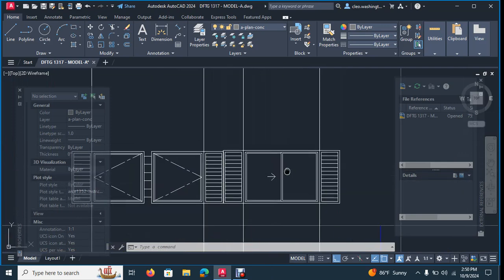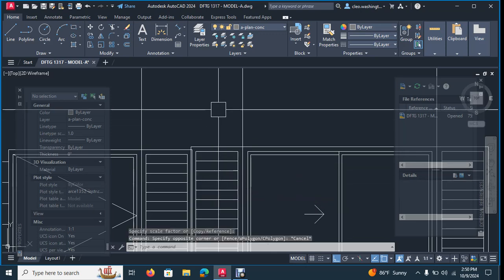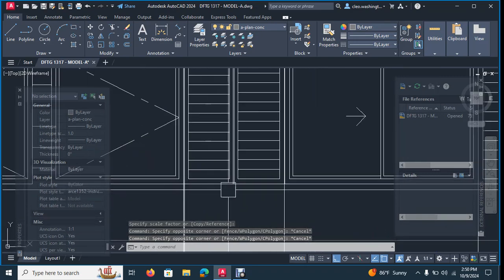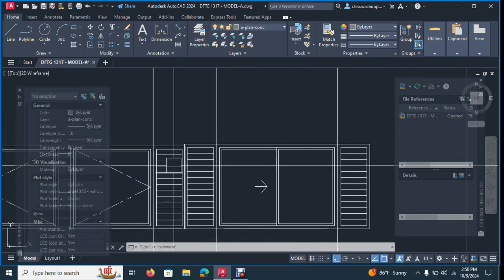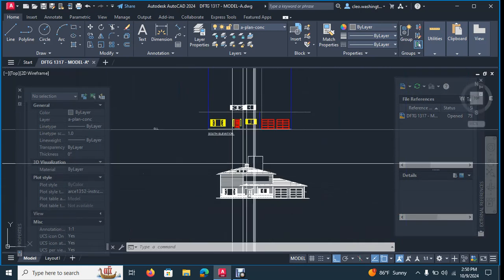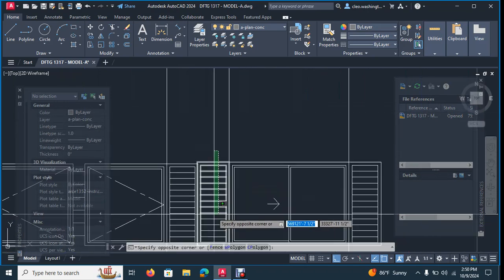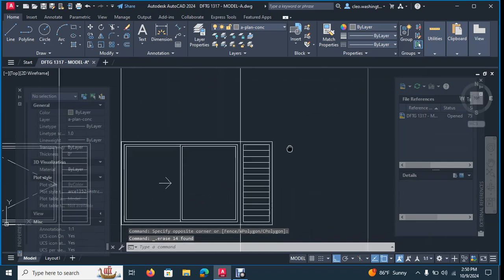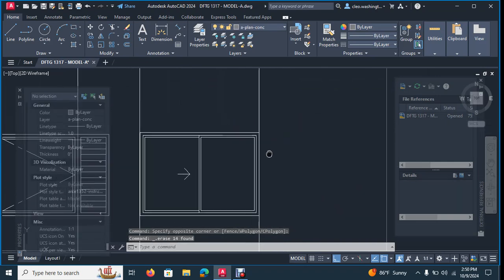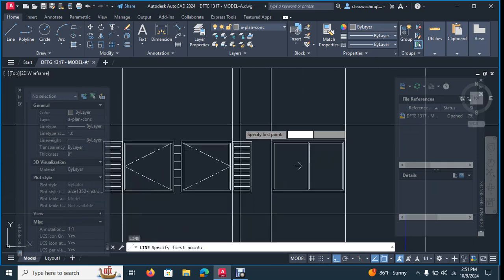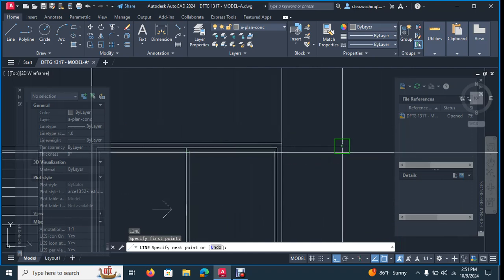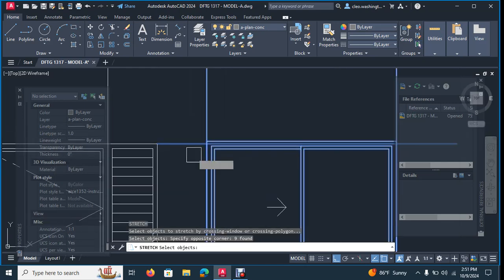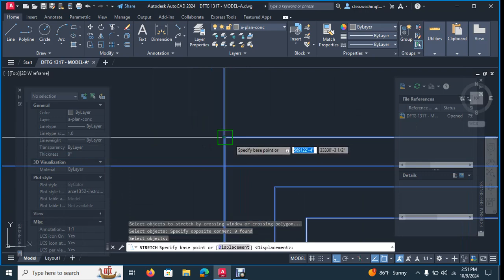So we have two different types of windows. So what we need to do is, let's go ahead and delete this shutter because the shutters are even all the way across the bottom, but the top, we need to modify this window because we don't want two different size windows, right? So let's go ahead and delete this, highlight it and hit delete, and let's delete this shutter. These are shutters, okay? Now let's take a line and draw it across here, and hit S for stretch, and you want to select every point that you want to move. So you want to come right here and here. And now let's take this line.